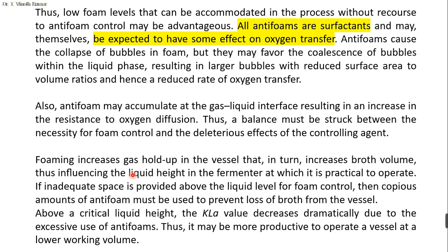And foaming increases gas holdup in the vessel, which in turn increases the broth volume and influences the liquid height in the fermenter at which it is practical to operate. If inadequate space is provided above the liquid level for foam control, then a copious amount of antifoam must be used to prevent the loss of broth from the vessel.